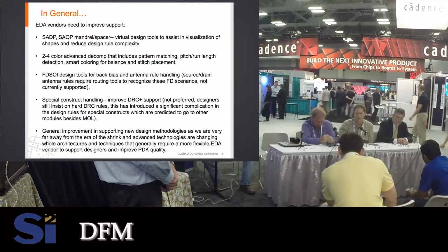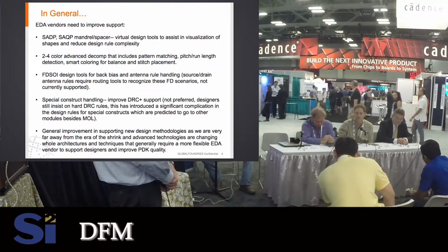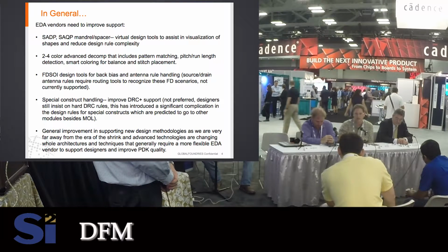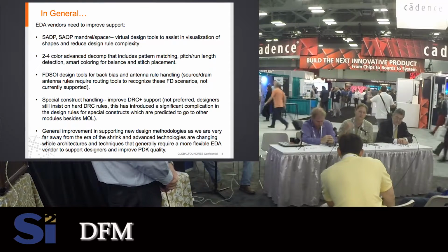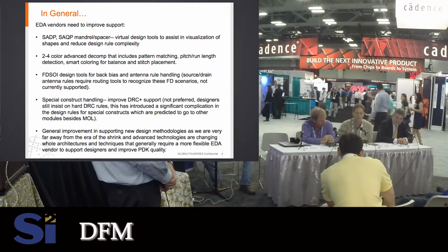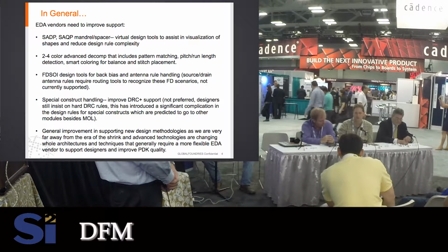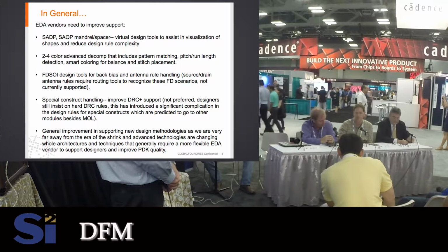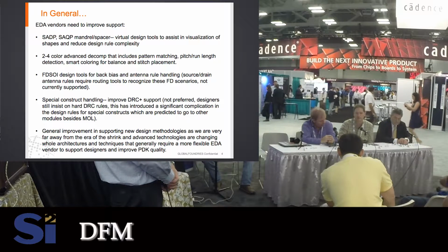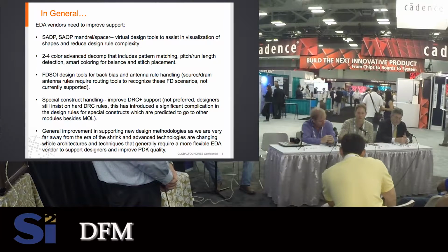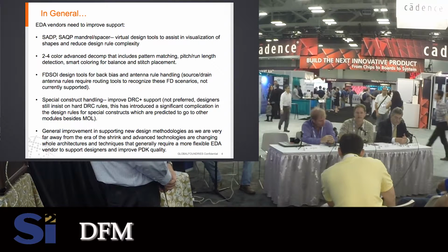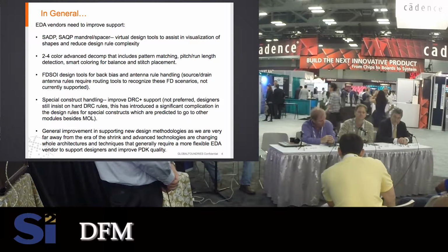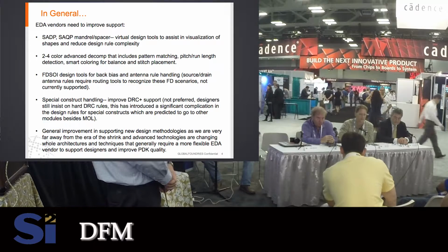It can be the same level metal, and in some cases where they're higher elevated, you may care about the distance and relationship to the next layer above or the next layer below. So it all depends on how your voltage dependent spacing rules are laid out for that technology node, what you care about as the layout designer. But it can be quite complicated depending on how high your voltage gets. Does that answer your question, or are you looking for something?